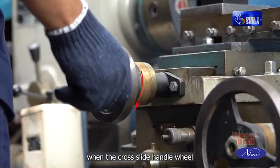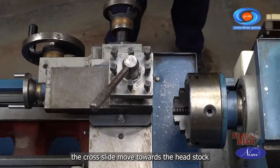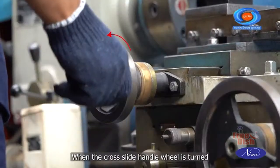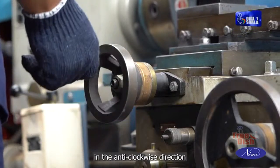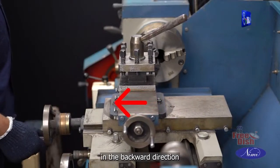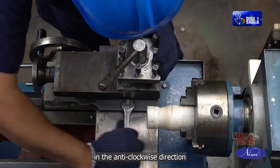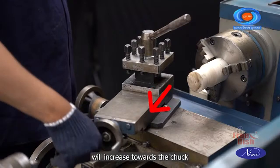When the cross-slide handle wheel is turned in the clockwise direction, the cross-slide moves towards the headstock in the forward direction. When the cross-slide handle wheel is turned in the anti-clockwise direction, the cross-slide moves away from the headstock in the backward direction. Swiveling the compound rest in the anti-clockwise direction will taper turn the job such that the diameter will increase towards the chuck.